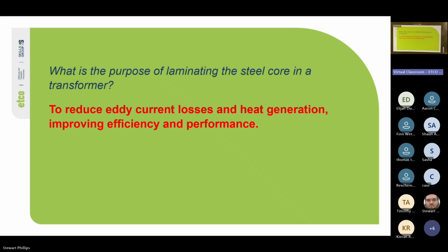area. If we think about our cable sizes, the more cross-sectional area, for example, 16 mm squared versus 6 mm squared, the 16 mm has less resistance versus the 6 mm. So if we have a smaller cross-sectional area, we increase the resistance. If we increase resistance, we reduce the current because the voltage, realistically, won't change. Resistance and current are inversely proportional. So it's because we increase resistance.